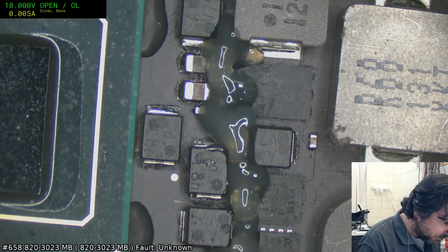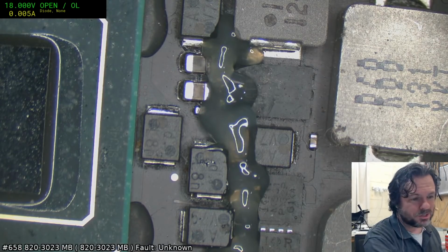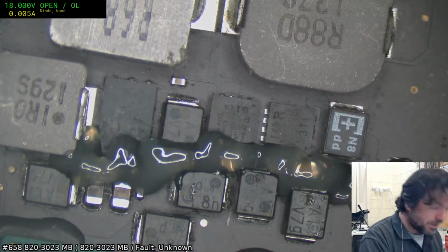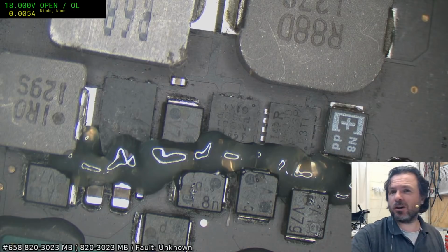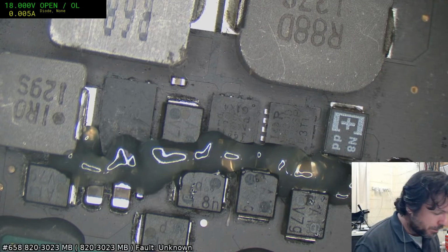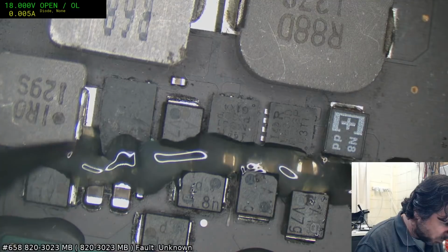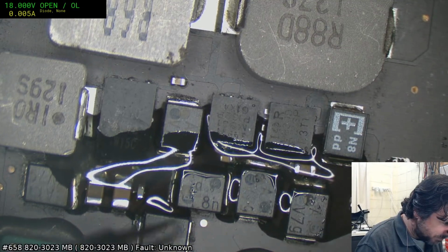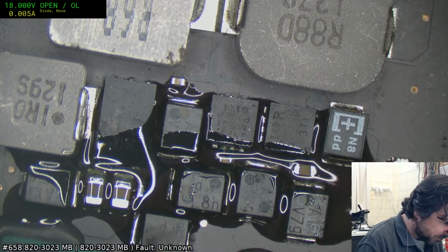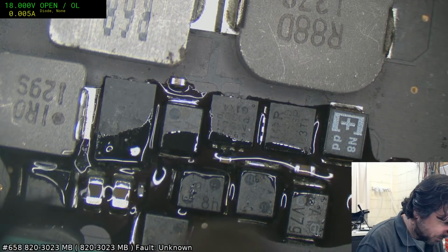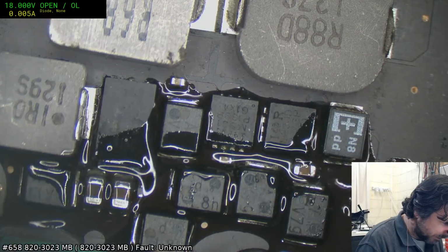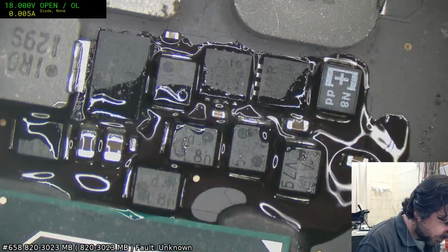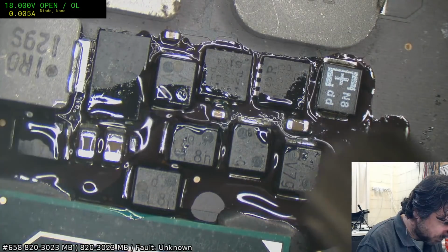Yeah, we like to blame that on the bending board, but really, if you look at the engineering of the case and the board, you are not going to get that much flex in those areas, certainly not enough to cause that kind of fault. In my opinion, those faults are caused by Apple pushing the part density too high, and the PCB and the layers substrate can't cope with the thermal differential, the difference between the thermal coefficients.